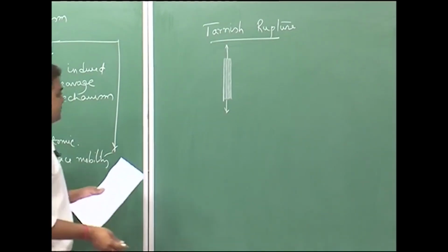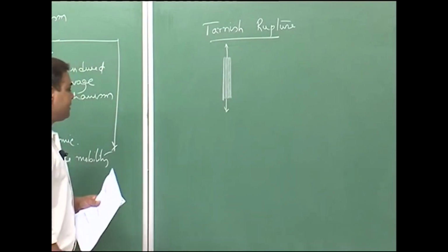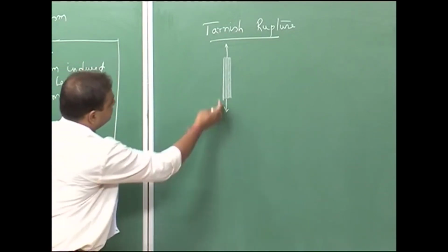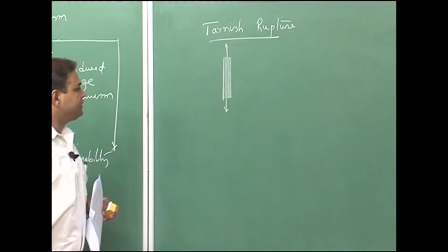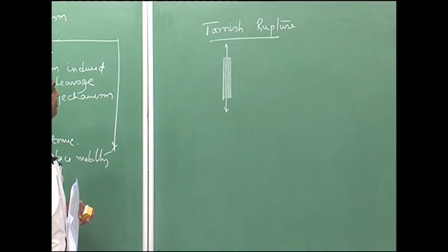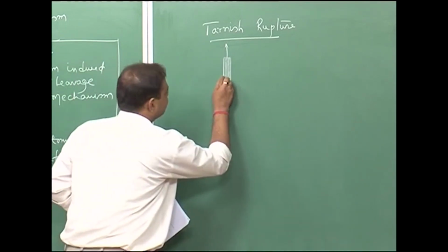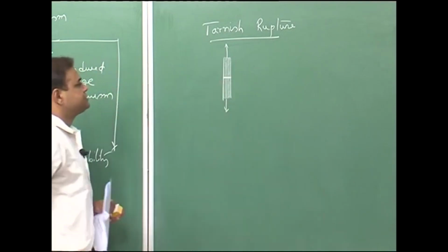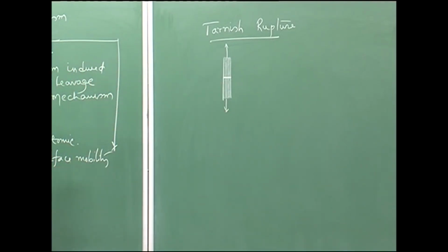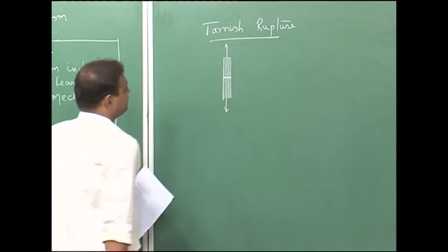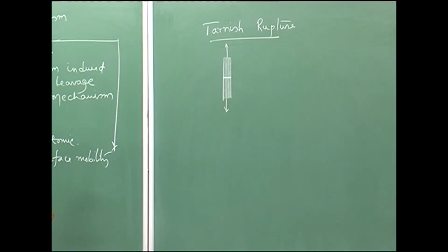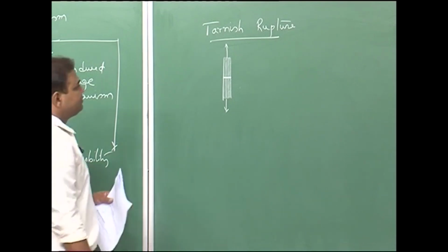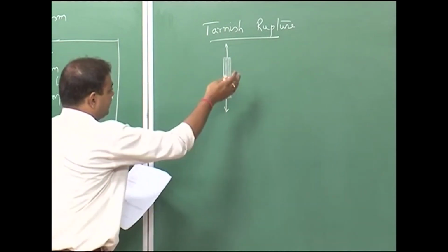Now, this passive film is brittle in nature, and due to the tensile loading on this brittle passive film, you can have a sharp crack. This is my sharp crack, which is getting into the material, and once it reaches this surface, it is experiencing a tough or ductile matrix, and then there would be crack tip blunting.